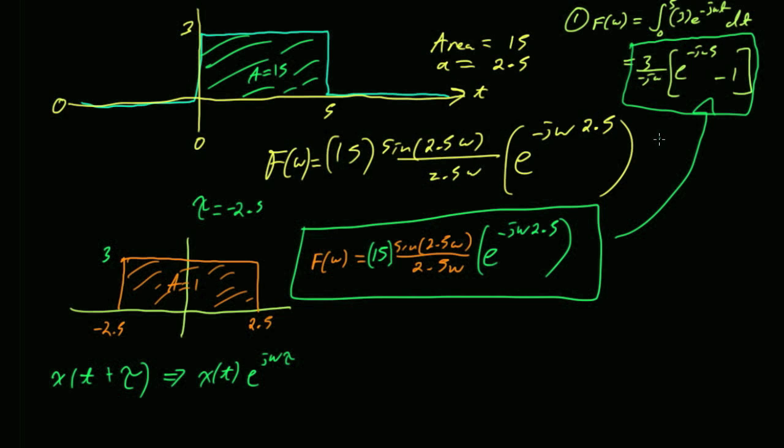So is it best to always start with a base condition like this, where it's easy to find the Fourier transform, and then apply it? I think so. It's easier because at the end of the day, what you're trying to derive out of this is a little intuition. If you just stick with the plug and chug, you're going to lose the real value in this. When I look at this, what I see is a sinc function, and I can calculate where that sinc function zeroes out. It's got some sort of amplitude associated with it. That's kind of important. And what's this expression going to do?